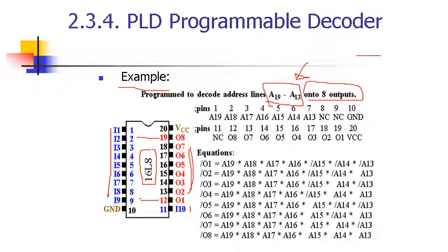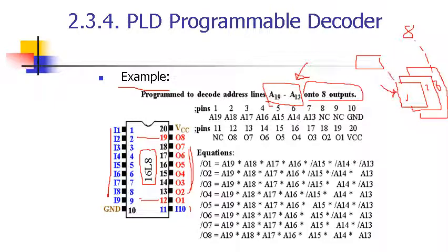So you have a microprocessor which is connected to maybe one, two, three, up to 8 different memory chips, and we need to select one of these 8 at a time. How do we do so? We're going to use the output pins O1 through O8 to select one of these 8 chips.